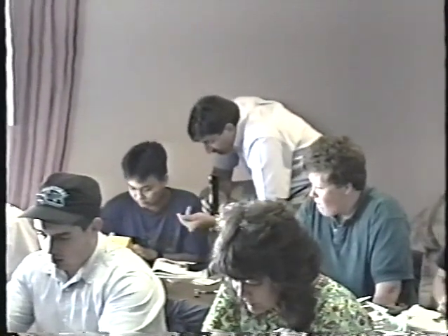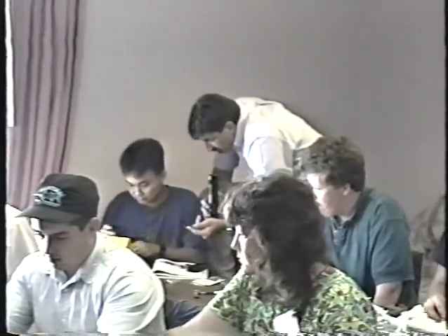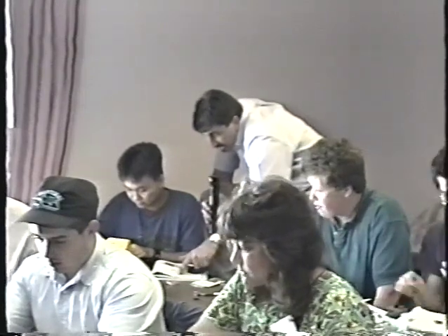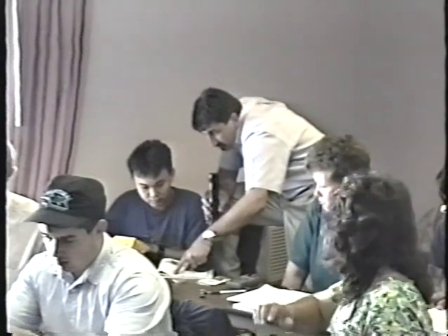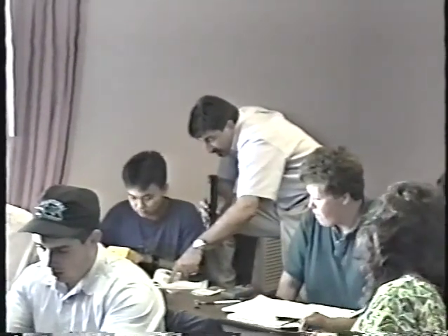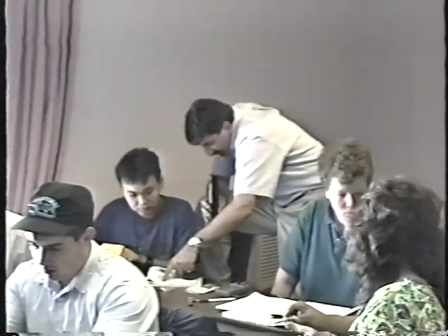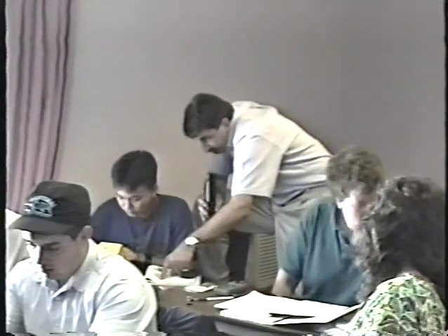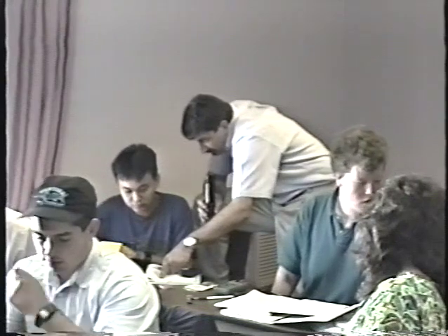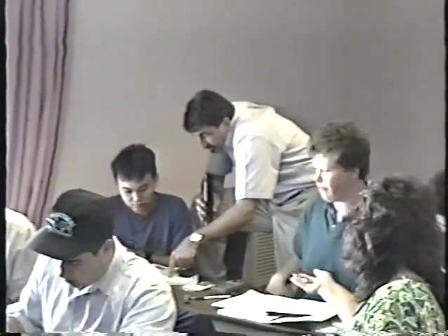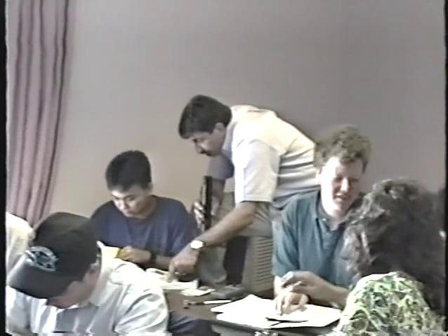Now reverse the leads in your hands. Same test. This time with the black lead on the base. Junction drop. Look, it's following. So far we got three that are perfect PNPs, right? Okay, leave the black where it is. Move the red to the collector. Junction drop. So far so good. Final check, collector to emitter. Should always be open.